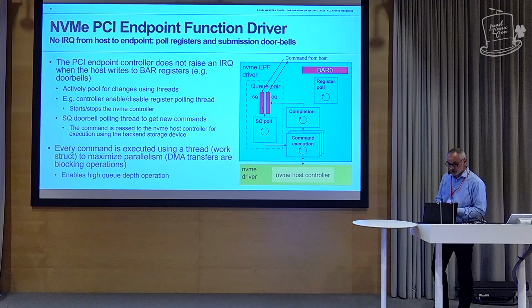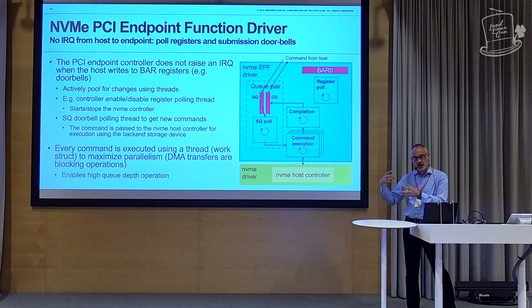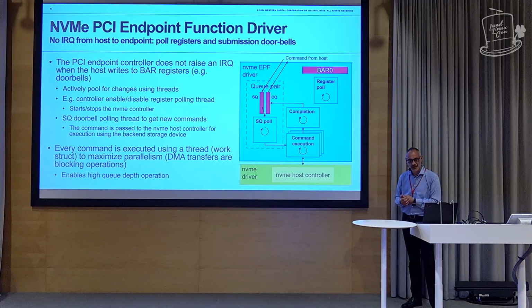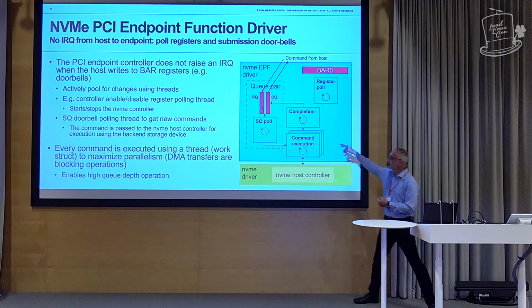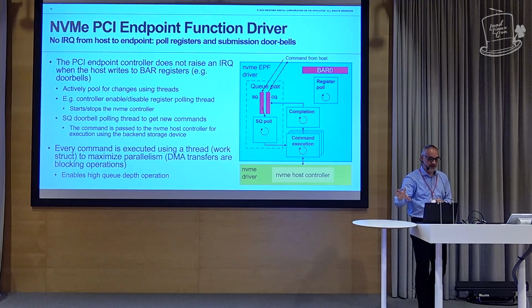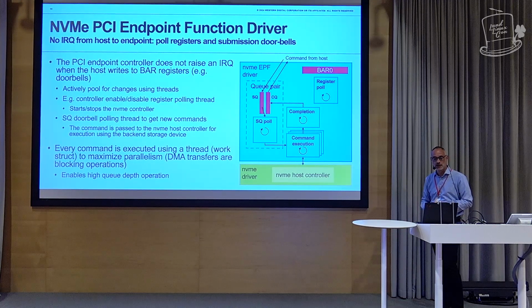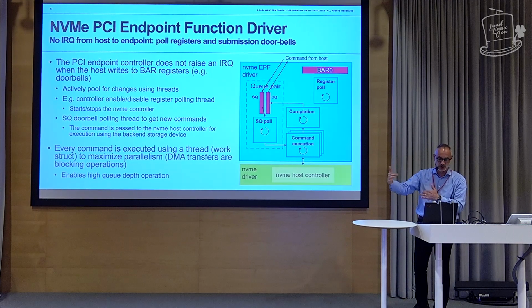And the completion is also a thread in itself, but that's just an optimization so that we can do a kind of interrupt folding so that we don't flood the host with one interrupt per command. So we essentially aggregate completions in this thread, put everything in the completion queues, and raise a single MSI interrupt for signaling a bunch of completions.